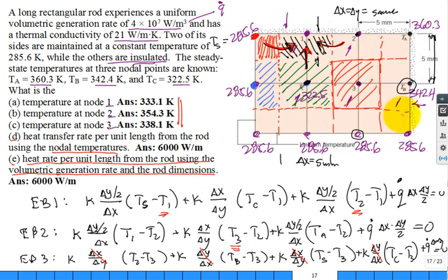Basically, everywhere in the rod, there is heat generation. So if I wanted to know what's getting to the surface out here that's uniform temperature, it's everything in the interior that's being generated. Q dot, this source right up here, times the area per 1 meter depth, and I picked 1 meter depth, hence it's 6,000 watts per meter.